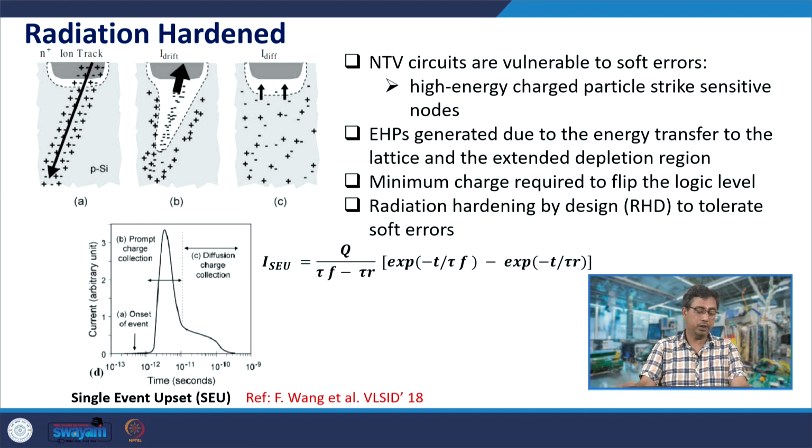So, these near threshold circuits have very small headroom. VDD minus VTH is very small. It can be negative, it can be positive, but it is very small. So, if there is a change in voltage at any node which is not the expected change, the impact of that is much more in near threshold circuits when compared with conventional circuits.